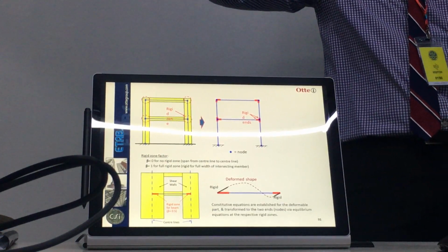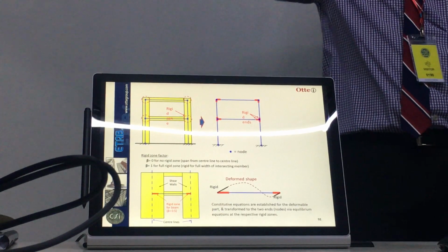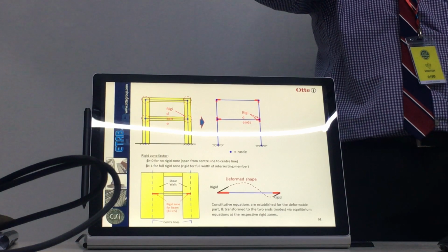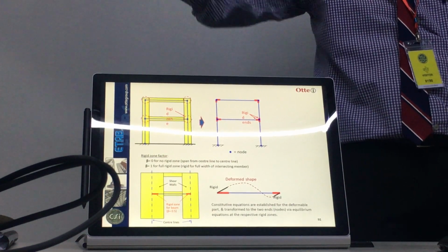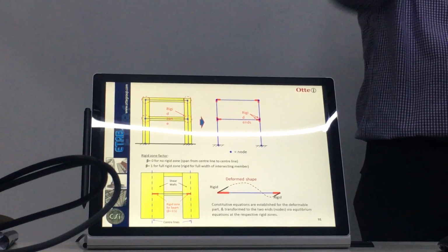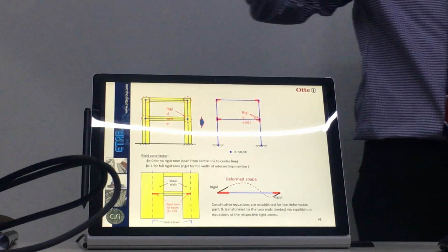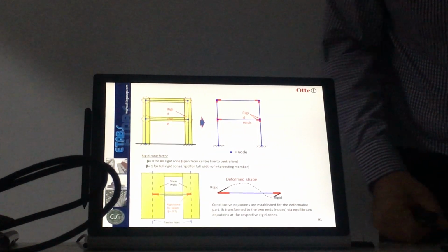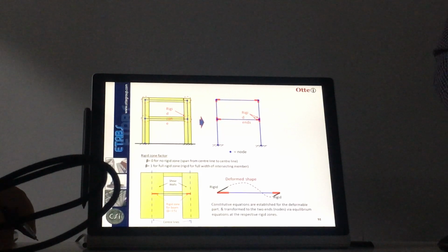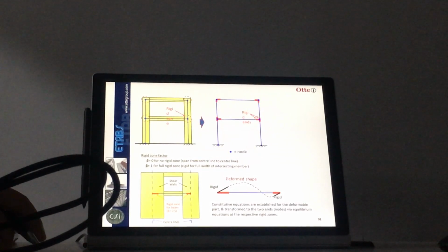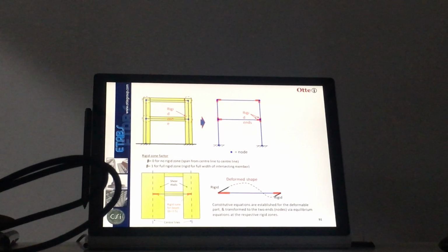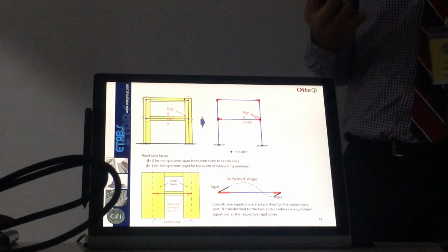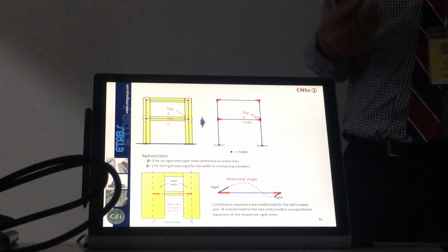Imagine that you have a beam, pin connected. So it flexes, right? Yeah. So under the uniform loading, you have this displacement, D, 100 mm, right? But now at both ends, 1 meter at both ends, you wrap it, make it stronger, encased in concrete. Same beam, right? Anyway, so that will change the behavior. So that's how we account for it. So basically, as an engineer, you will see that I will always account for this added joint stiffness to be more realistic in my design.